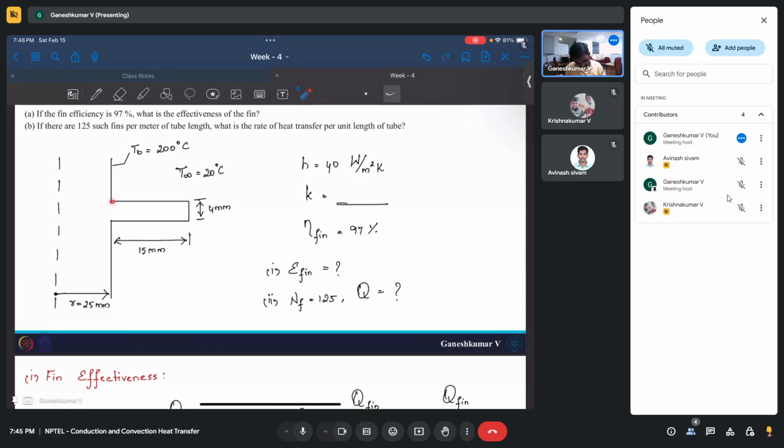You have surface area here, here and here. This is the total surface area. This is 2D, so you have to revolve this surface area along the center line, which means you need to multiply it by 2 pi. Once you know this, you just multiply with 2 pi and you will end up having the entire surface area.